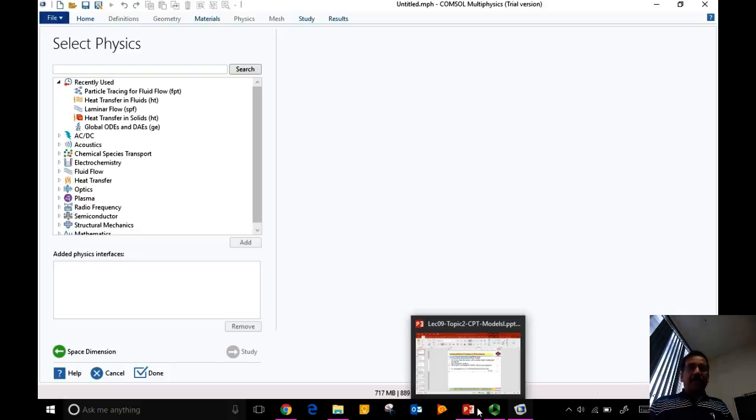Okay? So in the Taylor-Couette flow, in fact, it is through the instability that it develops the type of velocity component that we saw. I'm sorry, these things are not captured in the notes, but this is the geometry for Taylor-Couette flow, right? So we said in this case, V is going to be equal to Vr as a function of r and z, V theta as a function of r and z, and Vz as a function of r and z. But that is only after it passes through the instability and these cells form.